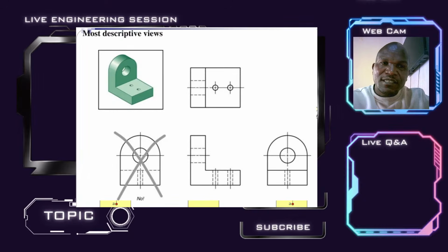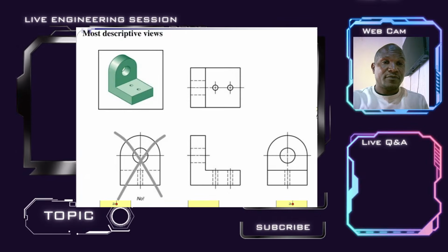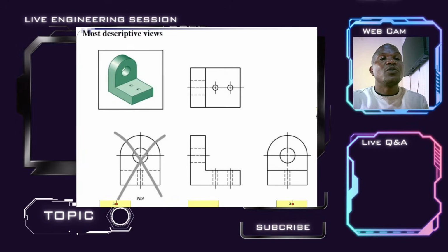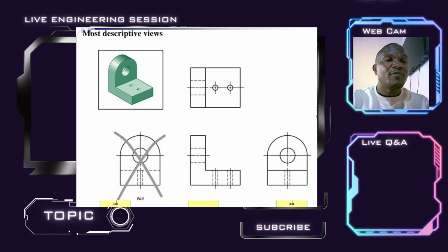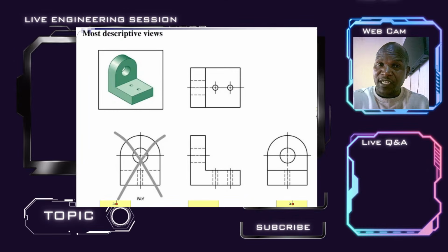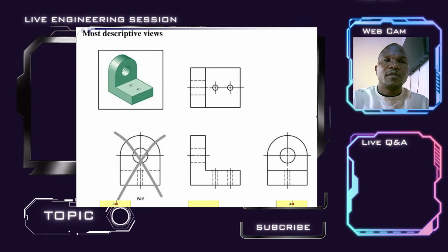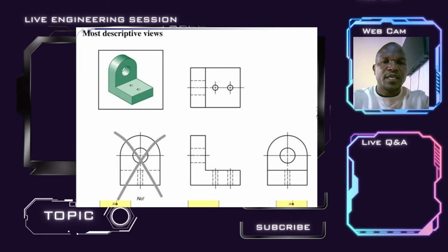Hence, the side view has been drawn from the right side, where we are viewing it. Later, I'll be able to explain that one. This is third angle projection. And when we move from first angle projection to third angle projection, they are one and the same apart from the plan, which interchanges. The side views are dependent on the point of view. The side views, pay attention, are dependent on the point of view. Let me proceed again to the next slide.